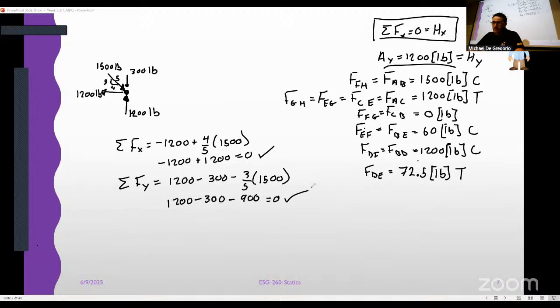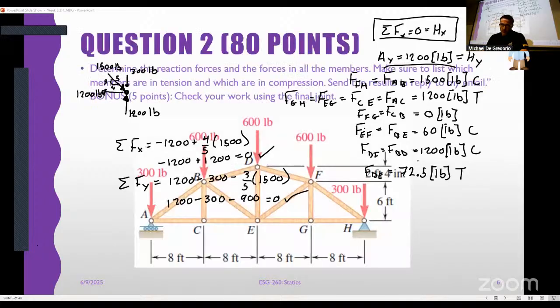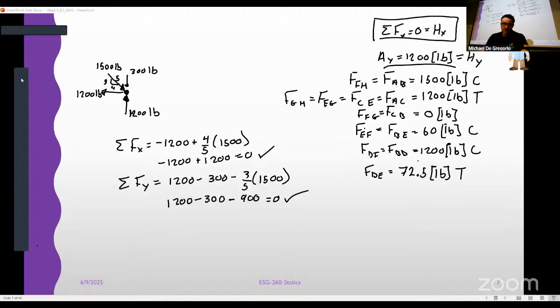I have a question. You had an 8x component. I thought that was a rocker. So let's see. No, this one's a roller over here, and this one's just a pin. It doesn't affect the overall method of joints, right? Because it's 0 in the x direction anyway. But yeah, a rocker will have a very pronounced curved bottom.